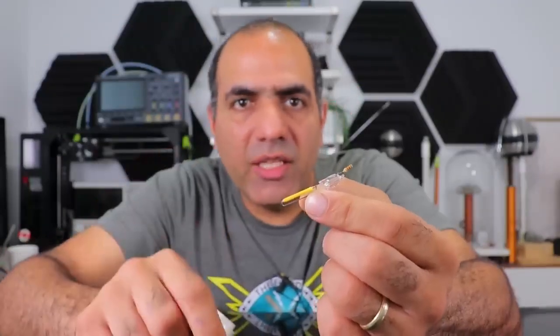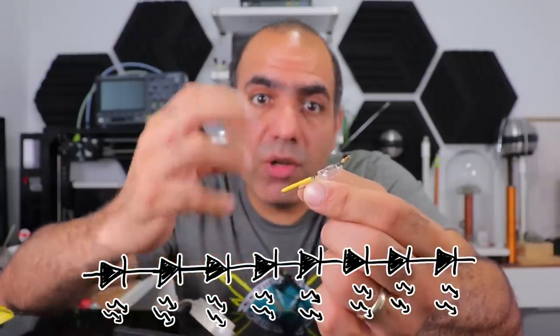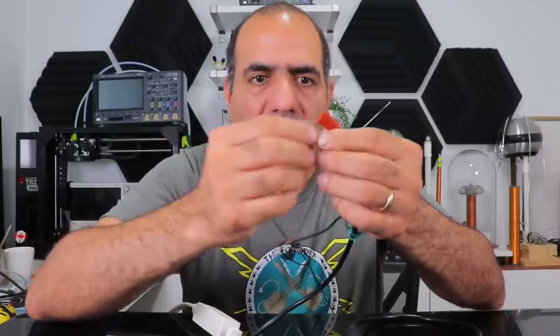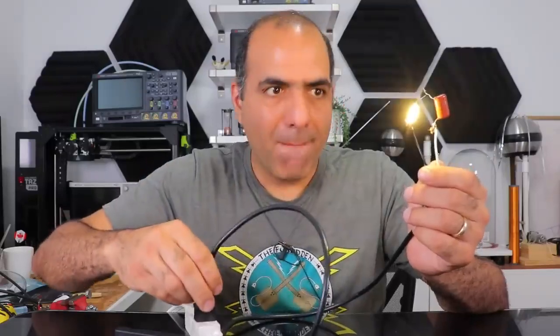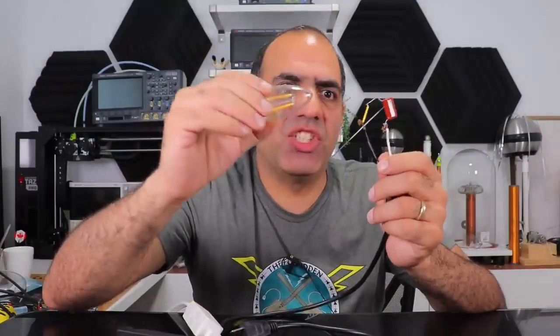And the string LED is basically a bunch of tiny LEDs in series, so it would require a higher forward voltage to turn on. Hopefully this string is not broken and my capacitor can limit the current through it. Here we are. Ha! It is working now. It burned? Yeah, it overheated. So I would need either a smaller capacitor for higher impedance and lower current, or a longer LED string so that there would be much larger voltage across the LEDs, so less current. But anyway, you get the point.